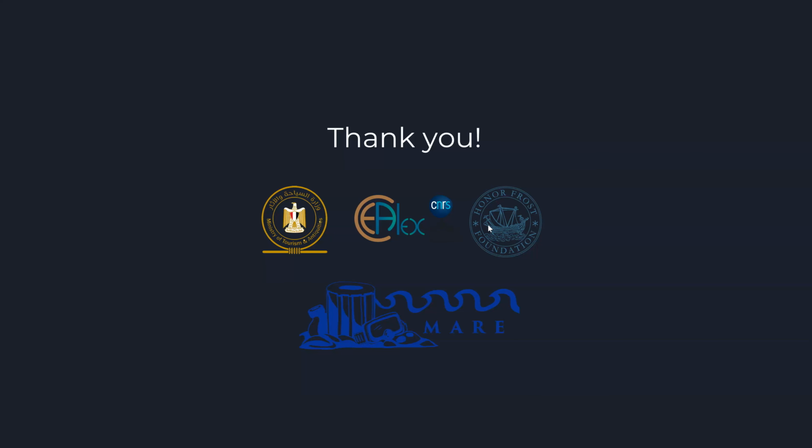Because, as I said, photogrammetry for the underwater site is done for a research purpose. As I said at the beginning of my presentation, we didn't do videogrammetry. We didn't capture with a fisheye lens, for a reason. In 2013 and 2014, we did a huge amount of experiments using both. That's why we decided to use a full frame camera with a 24 millimeter lens, and capture in RAW format. That's why we took this decision.